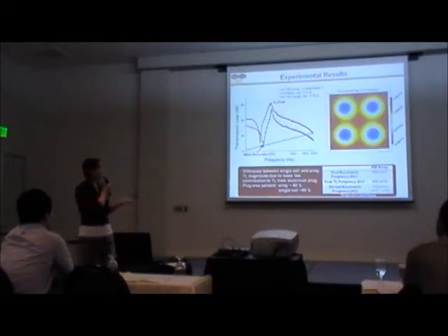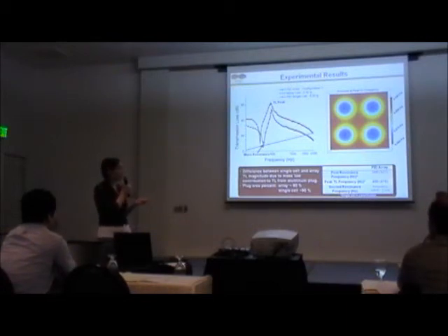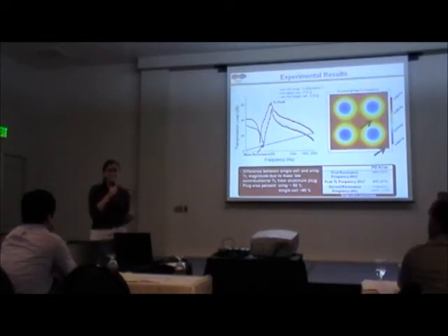Additionally, you might notice that the frequencies for the transmission loss peak and resonance frequency are shifted a little bit between the array and the single cell. Doing finite element analysis on this four-cell structure, the pressure distribution, you can see that between two adjacent cells, the pressure is lower than it is at the edge, where there are no adjacent cells. The result of this is that there's a pressure coupling between adjacent cells, and so the structure behaves as though it is more rigid than it actually is, and that's going to drive up the peak and resonance frequencies.